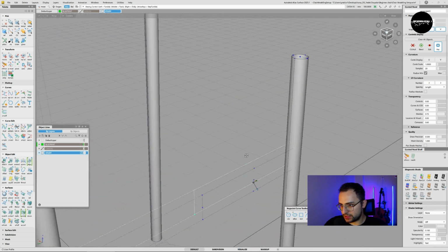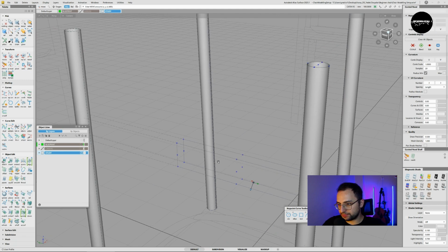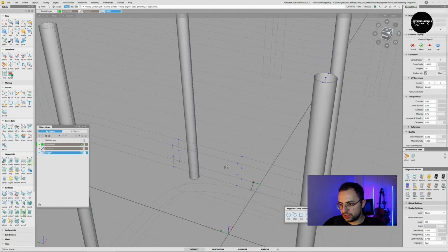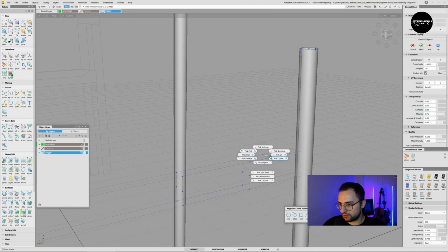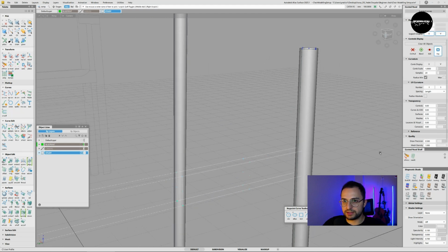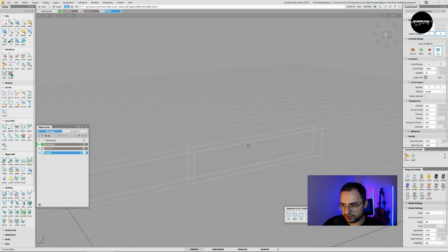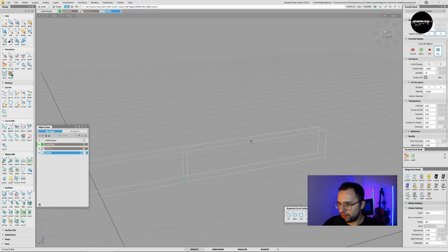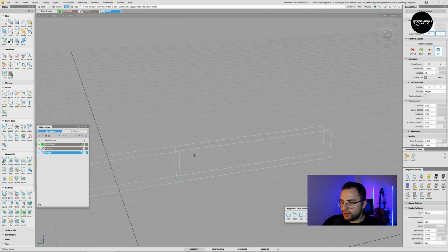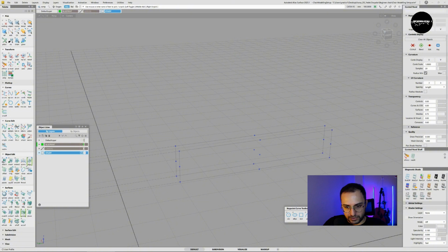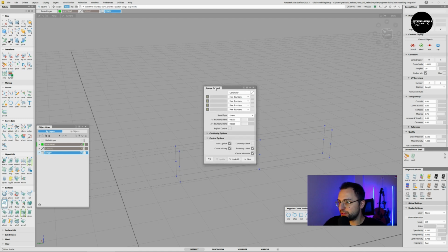Yeah, nice. So what I'm gonna do is pick these two rectangles and come here, display, hide unselected. That makes the other components gone and only the selected items left, so that I can see in a clear way. Let's create a square first, which is under the surface tab here, square tool. Let's double click that one. Yeah, we have several options here.